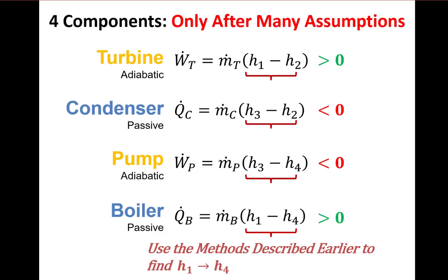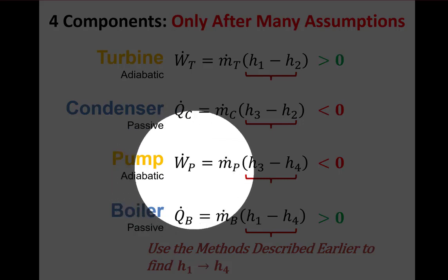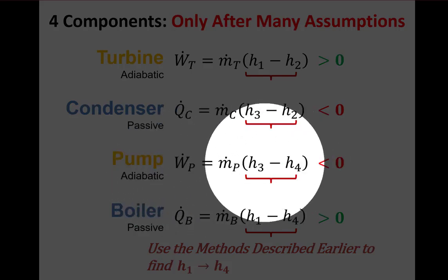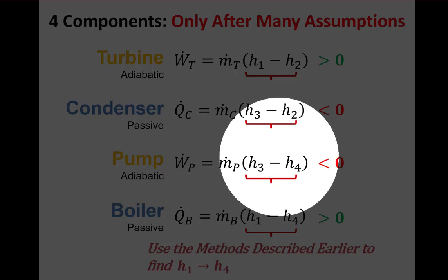And then, after you do these, you started with your conservation of mass, then you did conservation of energy. Now you've got these equations and you say, what's the fluid? The fluid in a Rankine cycle is water or something like it. And you fix the states the way that you fix states for water. So you're going to look at the vapor dome. You're going to see if it's water in A2 or A3 or A4. And if it's a subcooled liquid, the one that people mess up is when they look at the ideal pump, they forget that it's m dot times specific volume times delta P.